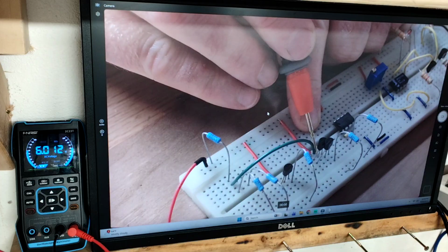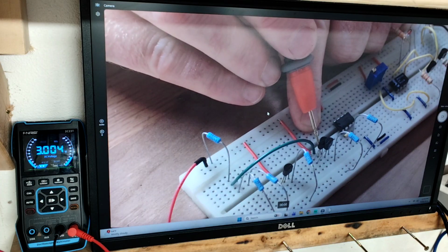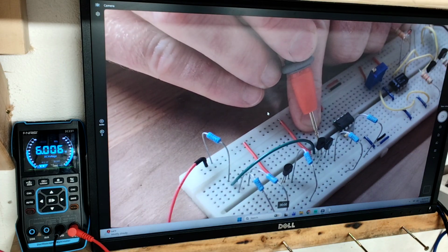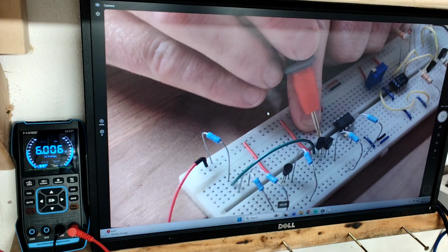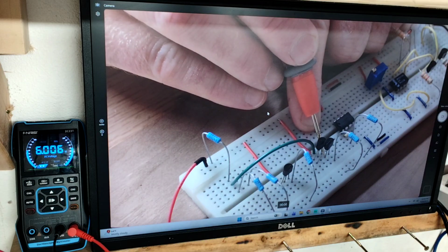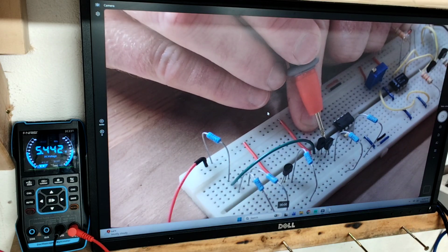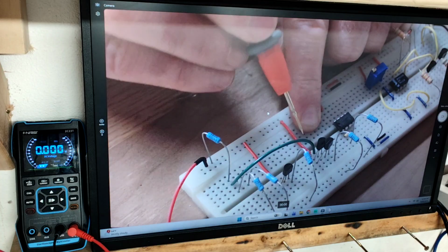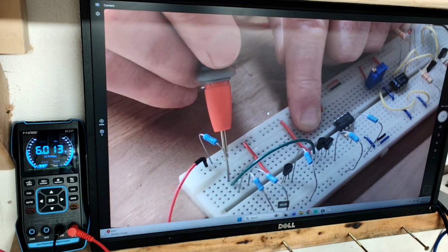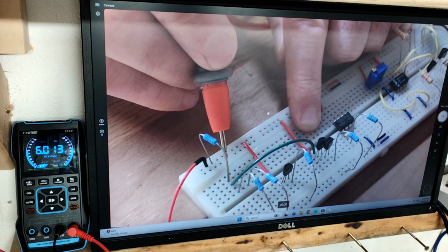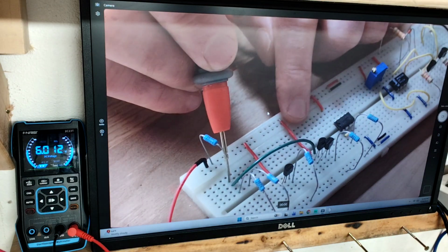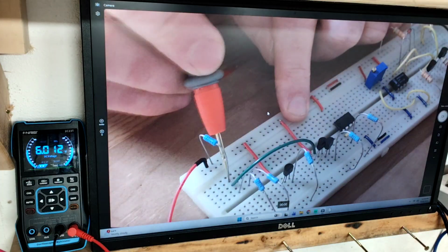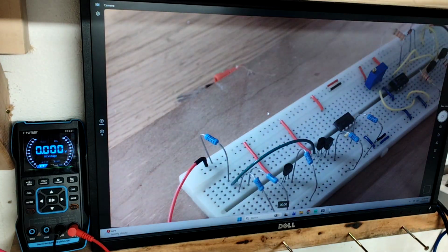So we have a very small drop there, 6.012 to 6.006. A tiny little drop across that because this diode's not doing very much work, which goes into the base of the next transistor and comes out here. So we've gone through 2 transistors and now we have a 5.4 volt output. So slightly lower, but the drop that we have here is basically negligible. Okay, let's see what the simulation results look like so that we can see that in a really precise way.